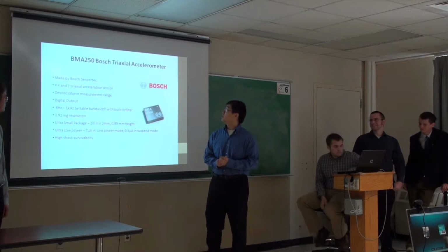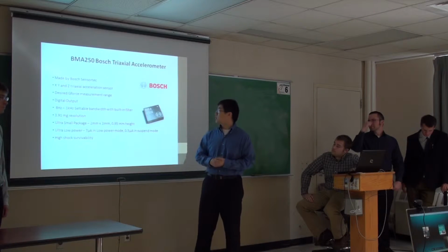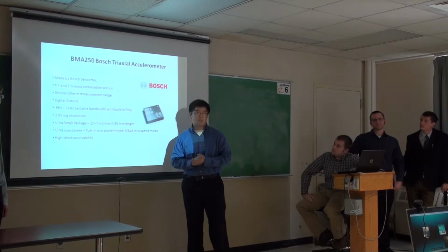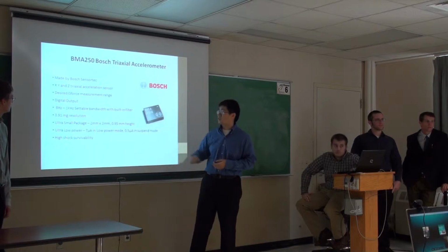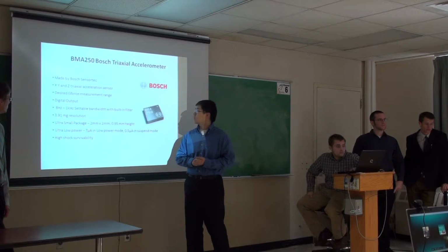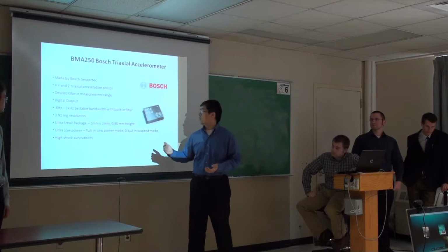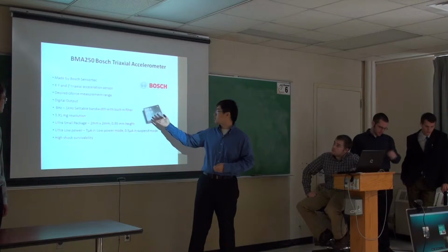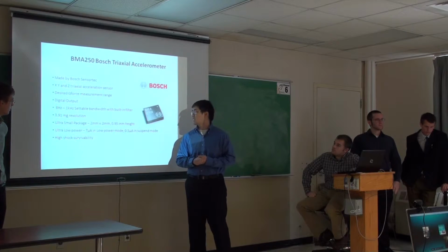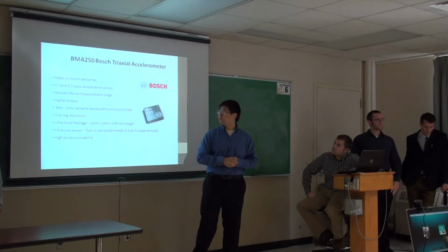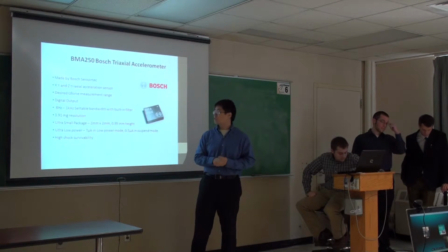The accelerometer that we use is the BMA250 by Bosch. First of all, it is made by Bosch, which is a requirement because our sponsor has a deal with Bosch, and you can get both of these at a discounted price. It's an XYZ triaxial, which is another requirement. The range goes from plus or minus 2G all the way up to plus or minus 16G, settable by the user, so it fits perfectly into our plus or minus 6G requirement.